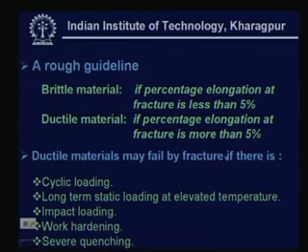Now, one of the situations is what has been mentioned over here: the ductile materials may fail by fracture if there is cyclic loading, long term static loading at elevated temperature, impact loading, work hardening, severe quenching. So, what are these concepts? Suppose, what is cyclic loading? Cyclic loading is a fatigue loading, which we will be learning after some time.